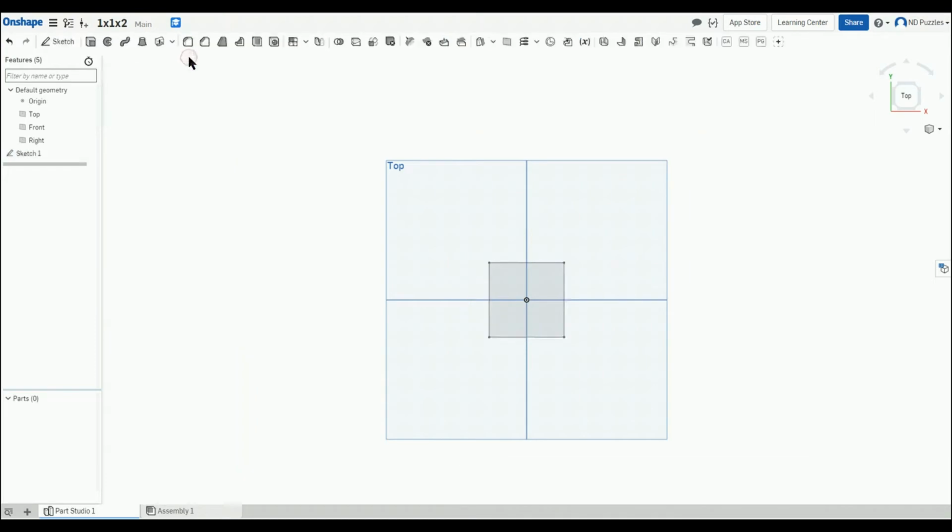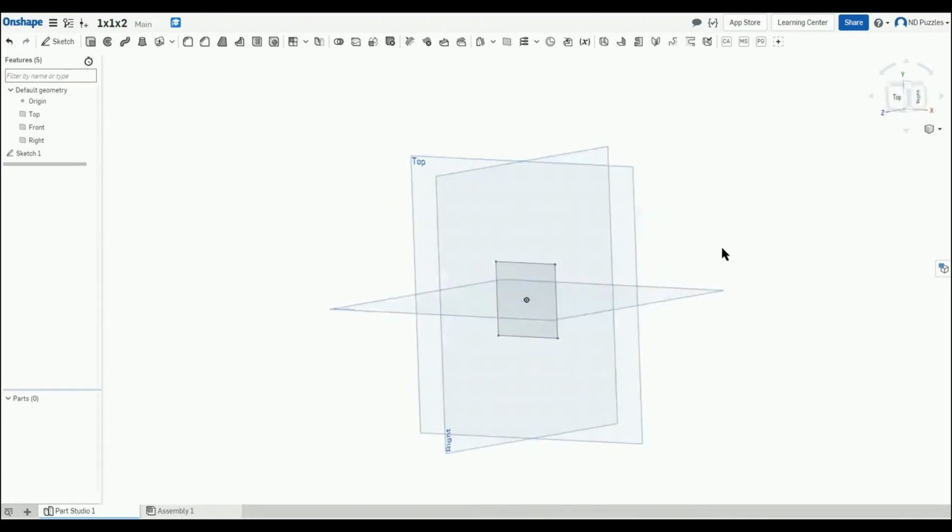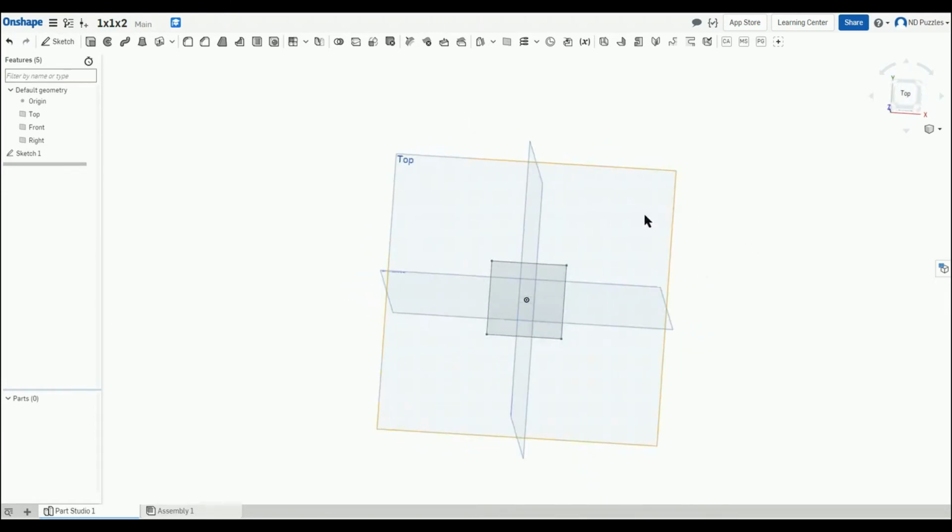For later steps you will want to have a rectangle or a square that is somehow connected to the origin. That is why I chose a so-called central pointed rectangle. You can access it by hitting the drop down arrow next to the rectangle. Now choose that shape and you will notice that our mouse turned into a cross. Try to fetch the origin with this cross and click on it. If you now move the mouse, you can choose the size of the rectangle. Click anywhere to set the rectangle.